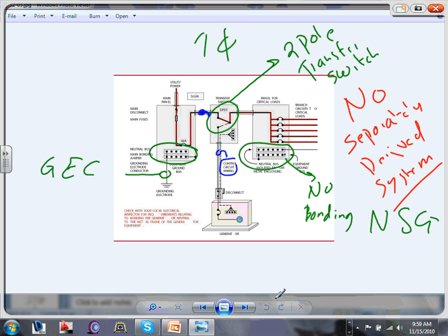Okay. The reason for that one, guys, is because you have multiple 2 meg generators here. You don't want these 2 meg generators to depend on the electrode grounding system of the service. You want to completely isolate the building from the grid. Okay, that makes sense, because I was thinking that's how we did it, but it's been a while. Separately derived system.